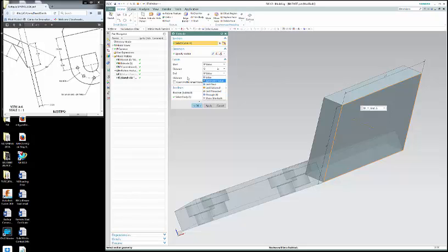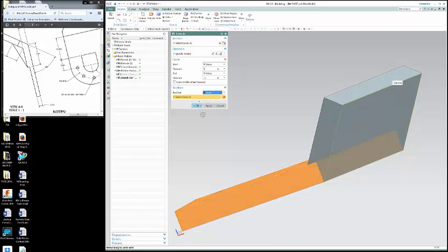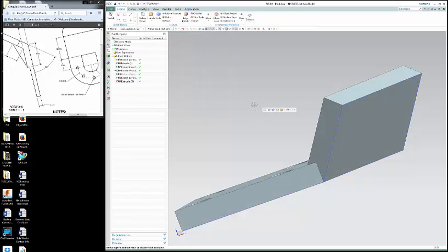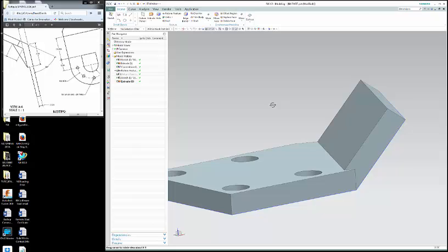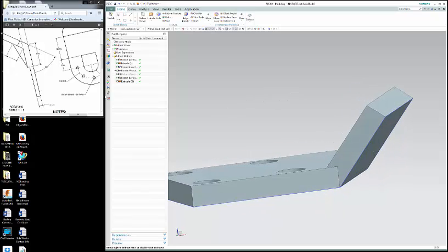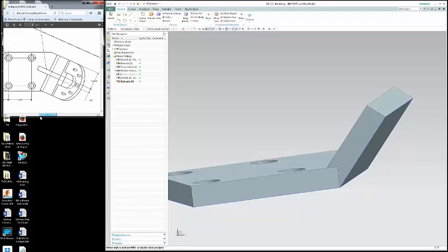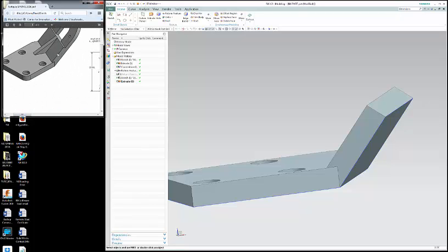And we do want that Boolean operation to unite, and we'll hit OK. And there you can see there's a nice clean part there. So that got the bottom half of that. So if you will, it got this area right here. It was 2 inches from the bottom here up, so that's where we had to go 2 inches there.